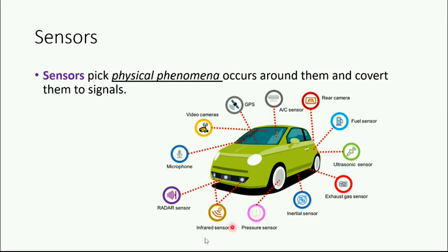That is the information. For infrared, while parking, if there is any block in front of the car, the infrared sensor emits light and measures the time of arrival of the light getting back. So that time is used with the velocity of light, which is 3 into 10 power 8, and then you can find the distance, and that data is transferred to the driver.